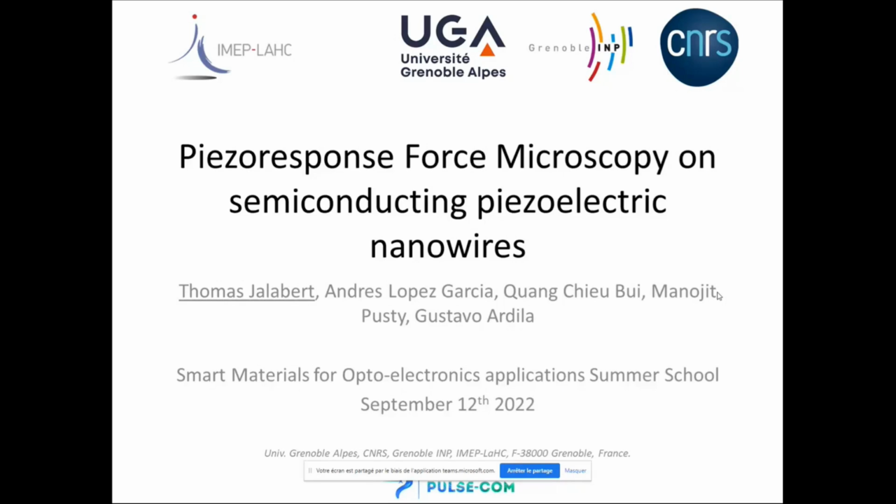My name is Thomas Jalabert. I'm a postdoctoral researcher in IMEP LAC in Grenoble, and I'm working on semi-conducting piezoelectric nanowires. We use characterization techniques which are based on atomic force microscope, and today I will present one of these techniques, which is piezo response force microscopy.